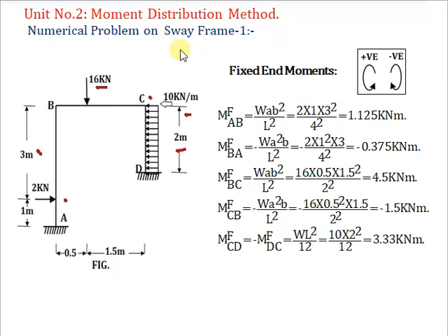This is a problem based on sway frame. Now this problem we have to solve by considering frame as non-sway frame. So let's first find out fixed end moment. Our sign conventions are anticlockwise positive and clockwise negative.